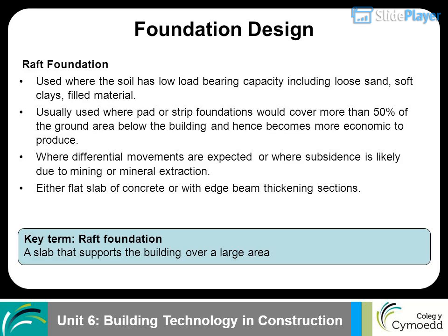Foundation design: raft foundation. Used where the soil has low load bearing capacity, including loose sand, soft clays, and filled material. Usually used where pad or strip foundations would cover more than 50% of the ground area below the building, and hence it becomes more economic to produce. Where differential movements are expected or where subsidence is likely due to mining or mineral extraction. Either a flat slab of concrete or with edge beam thickening sections. Key term: raft foundation. A slab that supports the building over a large area.